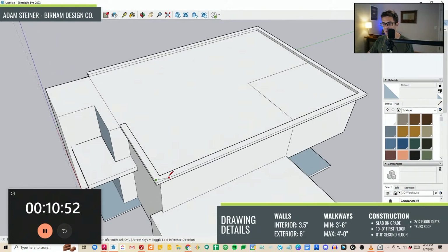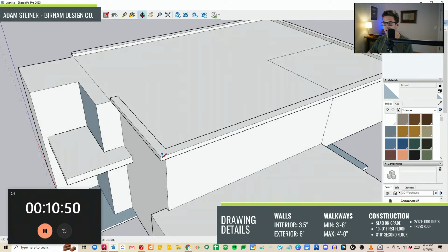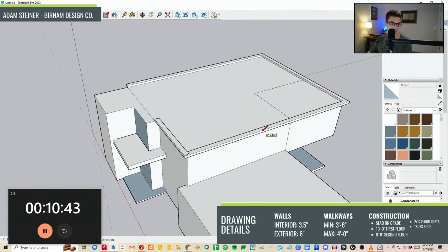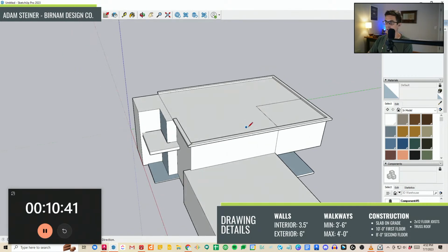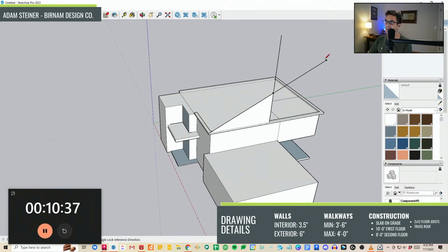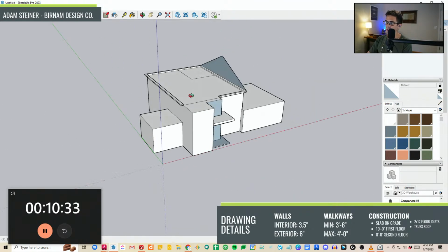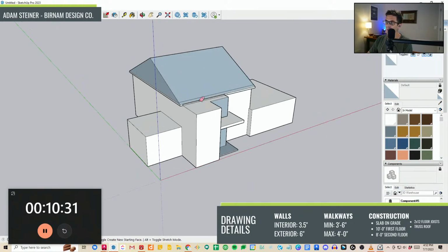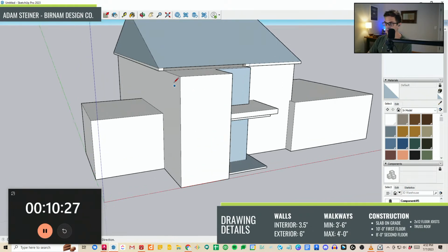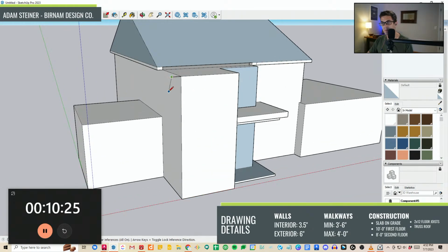I'm going to show simple. You know, I probably should show just 6/12. One, it's more affordable, and two, I think it's going to help it not feel as pronounced, because it is pretty deep front to back. So with a 6/12, although I might bump that up if these 12/12s project up over it. We'll find that out though. So I'm coming down 18 and 18, which gives me a 12/12 pitch.